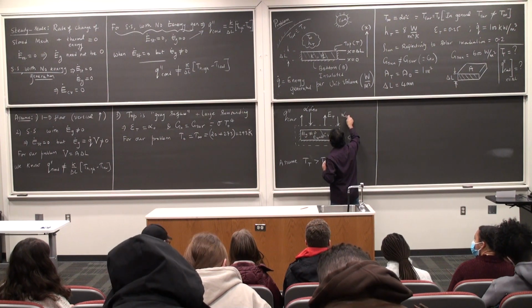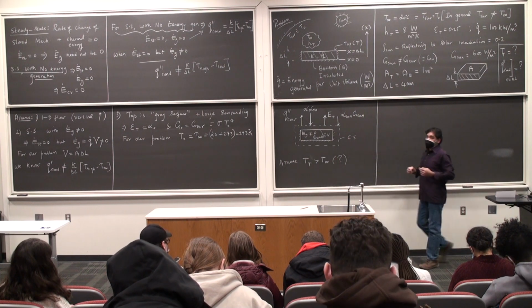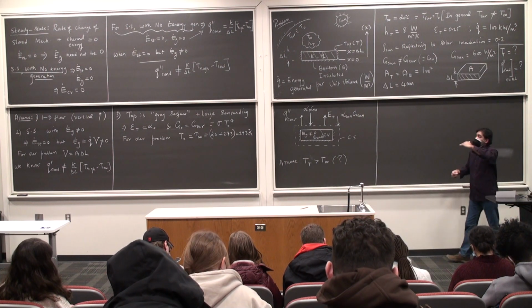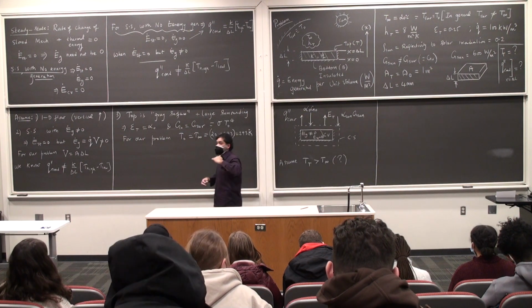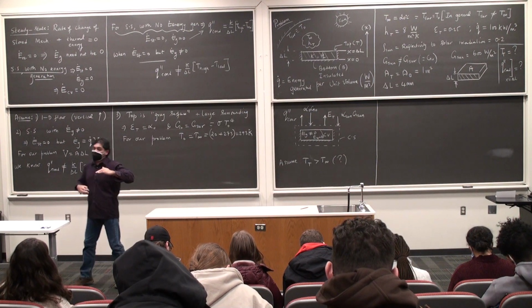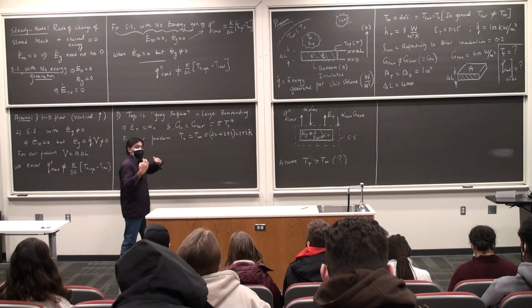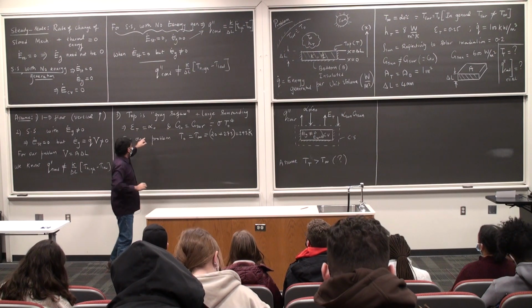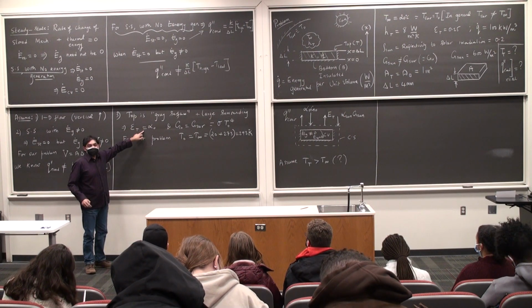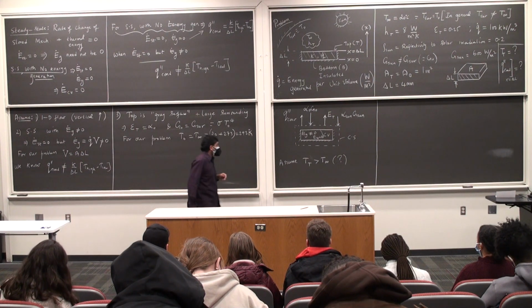This is alpha of the sun. Not alpha of the sun, alpha of the surface to the sun, I'm sorry. Absorptivity is a property of the surface. It's not a property of the sun. Emissivity is a property of the surface. It's not a property of the surrounding. The surrounding could have its own emissivity and absorptivity. If you have this special gray surface, then the following is true. Under what caveats is this true? We will see radiation heat transfer later.